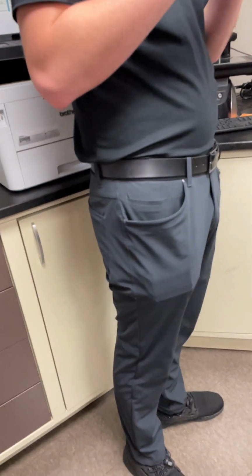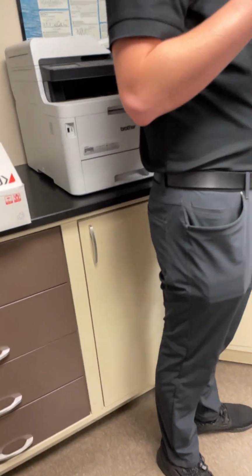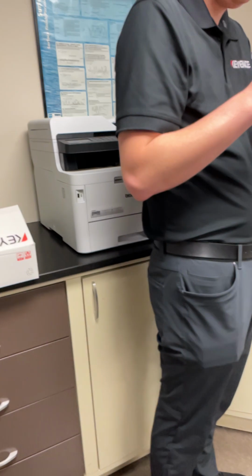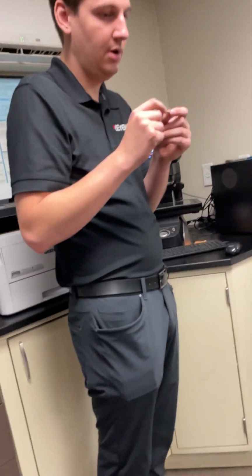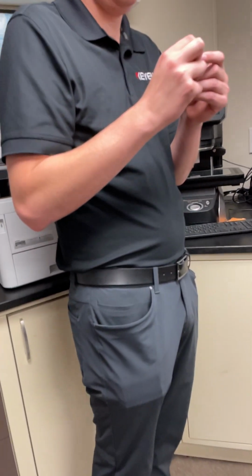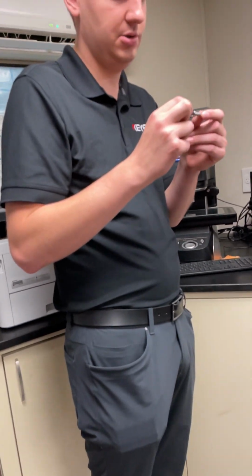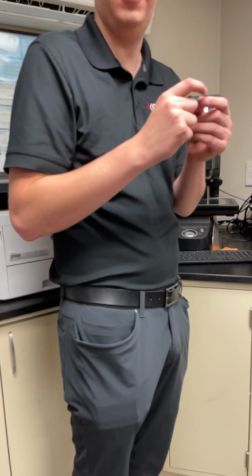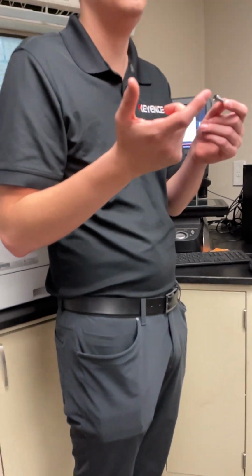If we had a program for this where it didn't show that, and we ran one and it was the right diameter to a certain point and then had a taper in there, would it show that, whoops, this is not right? What I would do is a line to line, and then I'd also do an angle measurement and make sure that angle is within a certain tolerance. So if it goes within or out of that, it'll flag it.